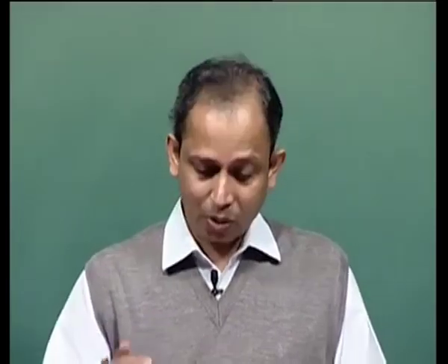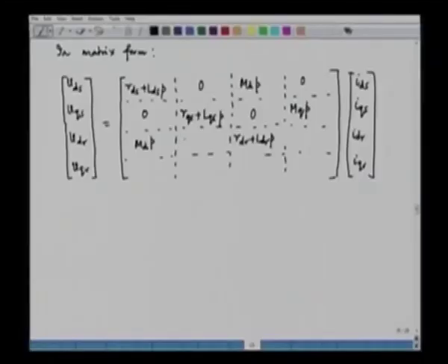It means the q axis flux will produce rotationally induced EMF in the d axis. So here we have minus omega r LQR, and also minus omega r MQ here.